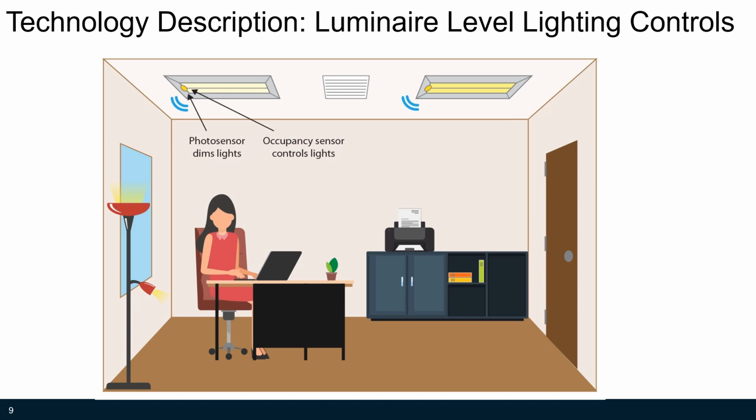This approach, in its simplest wireless form, simplifies lighting control system programming, making it more likely to work as intended and therefore delivering the expected energy savings. Beyond the capability to yield even higher energy savings than traditional lighting controls, luminaire level lighting controls also have the potential to reduce first cost by removing the need for control wiring, a considerable labor savings in a retrofit application. A wireless solution also makes the controls more easily reconfigured in response to changing needs within the workspace.